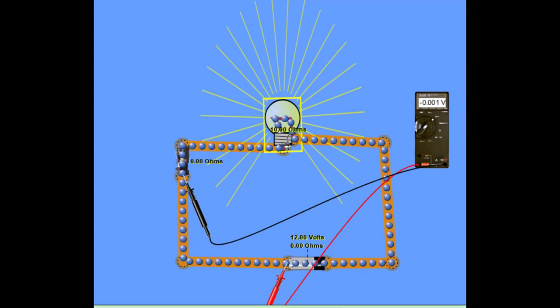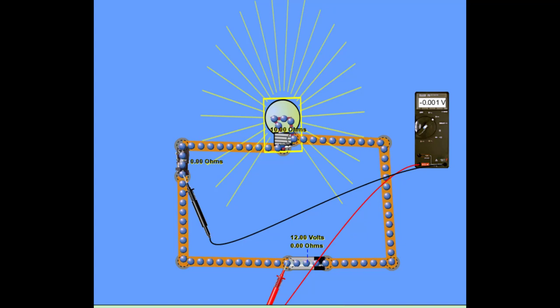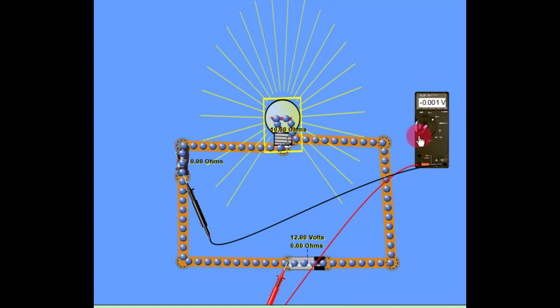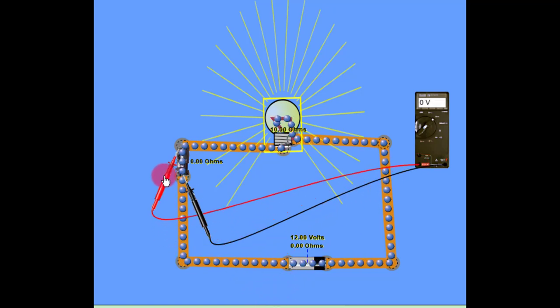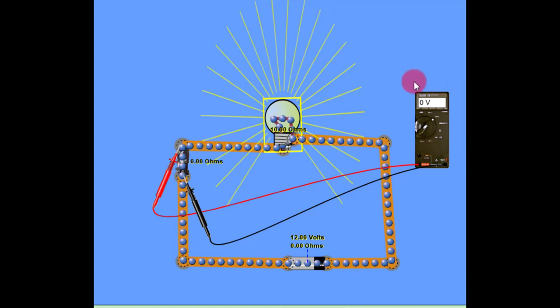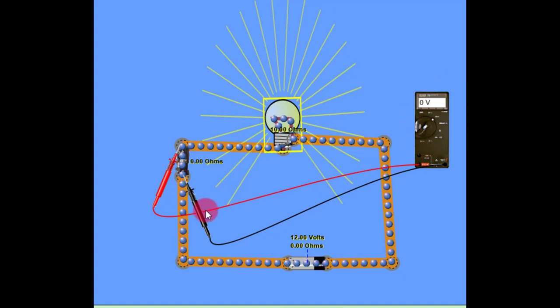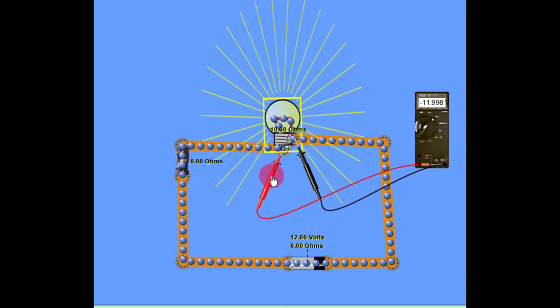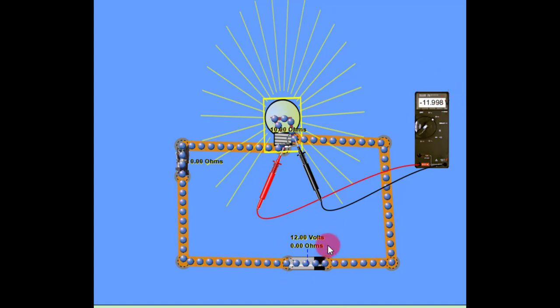On the diagram we just looked at, 41.3, it showed that it was 0. As you can see, there's always going to be a little bit, right? But it is basically, if we're rounding up, it's 0 volts. So if I put my lead on the other side of the fuse or the switch, you can see it's pretty much 0 volts. There's no voltage drop there. And based off of 41.3, if I put my lead on either side of the bulb, you'll see the voltage drop equals what's being applied.